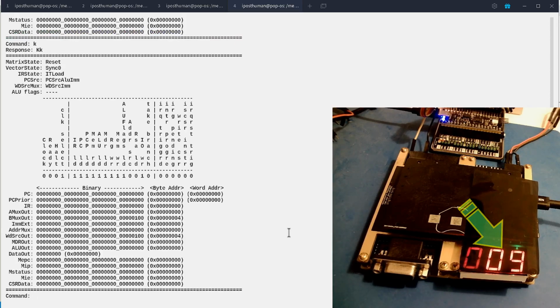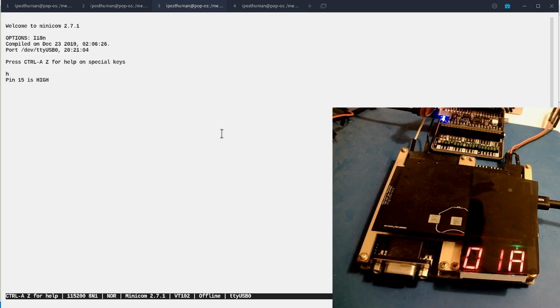That's why it stalled from 0 to 1, is just running through the boot. So now the program is running at 48 Hertz. I'll come back over here, and I'm going to artificially, well, in reality, generate a real interrupt. By doing that, I'm going to take the pin low, which is a falling edge, and that's how our code was set up, and bring it back high. And you can see that that triggered an interrupt, and for a brief moment the blue LED lit up.